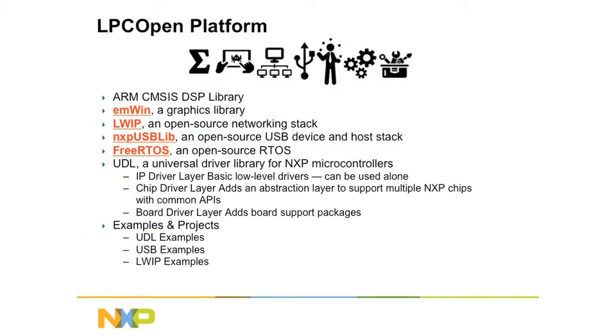And then to tie it all together, we have created something that we call the LPCOpen Platform. And this is basically everything that I've just been talking about. You have emWin, you have lwIP, you have the NXP USB library, you have FreeRTOS, and you also have driver layers. So you have driver libraries for all the peripherals on the chip. You have board support packages for the development boards that we come out with, so that you can develop against a common API regardless of which part or which board you're working on.